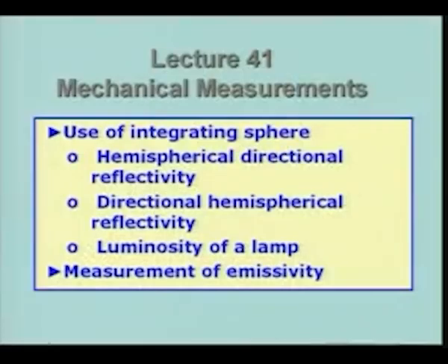Essentially what I am going to do is look at the use of the integrating sphere for two things. One is hemispherical directional reflectivity measurement, the other is directional hemispherical reflectivity measurement, and the third is a use which is usually for the measurement of luminosity of a lamp. I will describe it in some brief detail. Subsequently, I will look at the measurement of emissivity by various techniques.